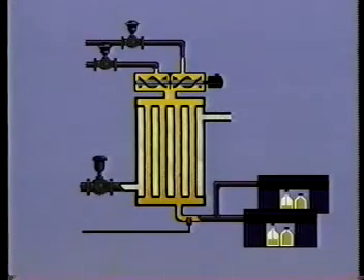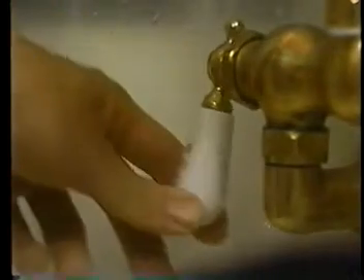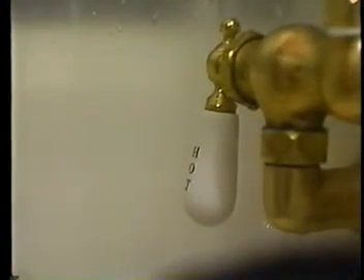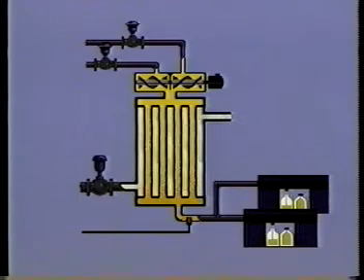The continuous process behaved in a different manner. The rate of heating was rapid, and there was no large mass of liquid to absorb the change from valve opened to valve closed. This we can compare to a shower. When the hot water valve is fully opened, the product, or a bather, feels the change immediately. When the valve is closed, the product is in trouble again. As the cycle repeats, the product continues to suffer because of the on-off control action. It is obvious that in this case, on-off action just doesn't work.